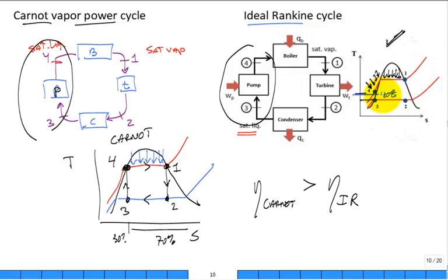Why is this wasteful? Why is that so bad for the performance of a heat engine? Well, you go back to Clausius's inequality, and you say that we want to bring in heat, Q. When we bring in the heat, we divide it by the temperature at which it comes in, and that's entropy coming in, right?